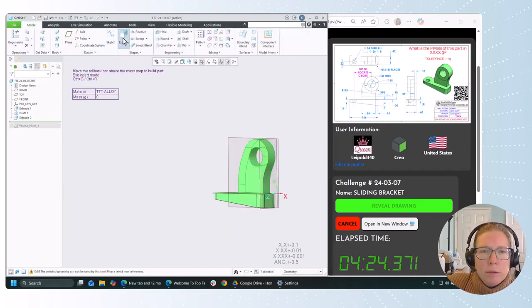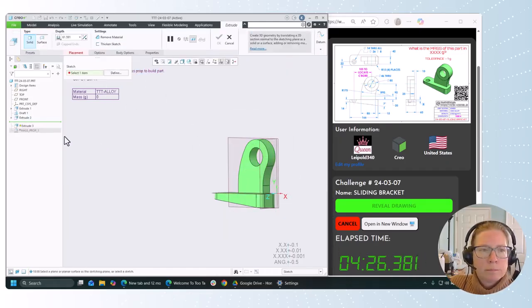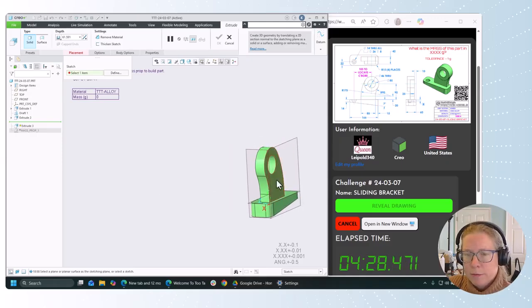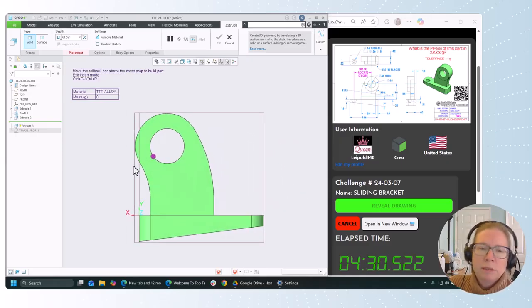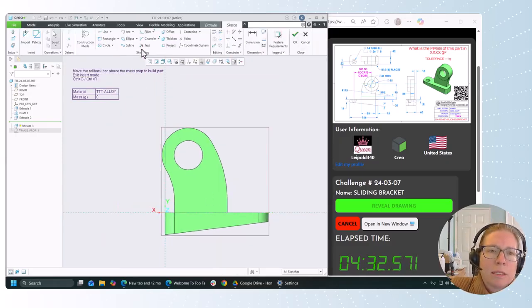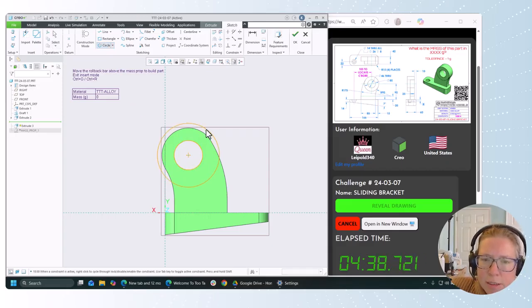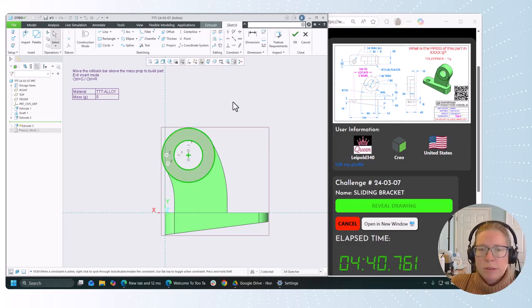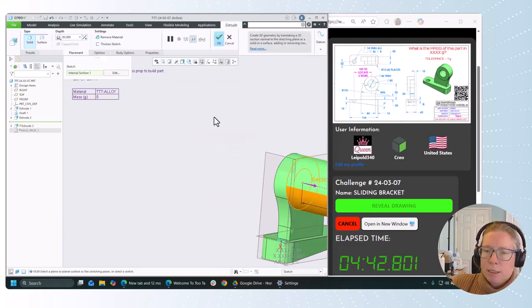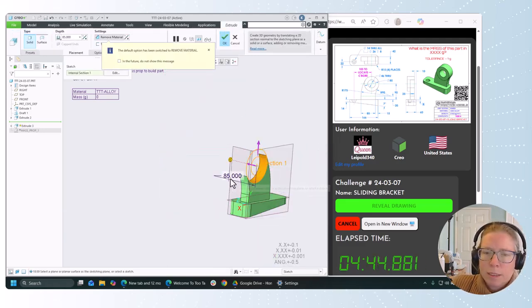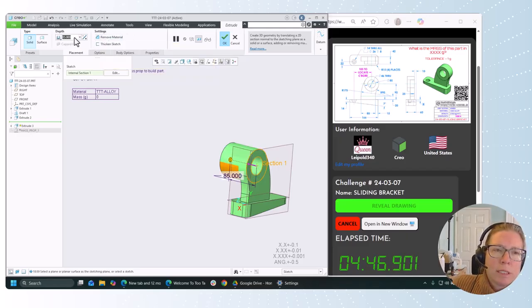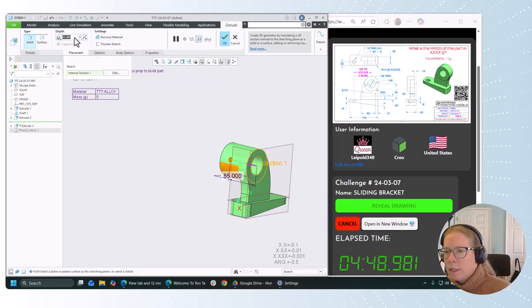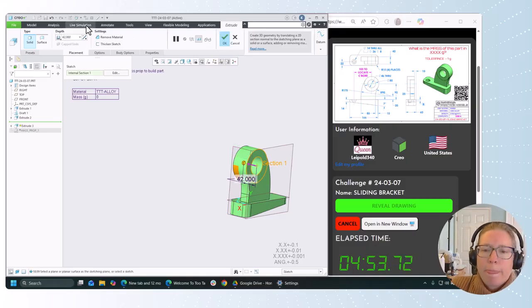And let's extrude from that same surface we used before. That's okay. Doesn't matter, let's go in the other direction. And while I could project this, I think it's probably easier just to go right onto the same circles. No extra dimensioning, and we're not removing that material. Overall, that has a depth of 42. It's in the top view there.